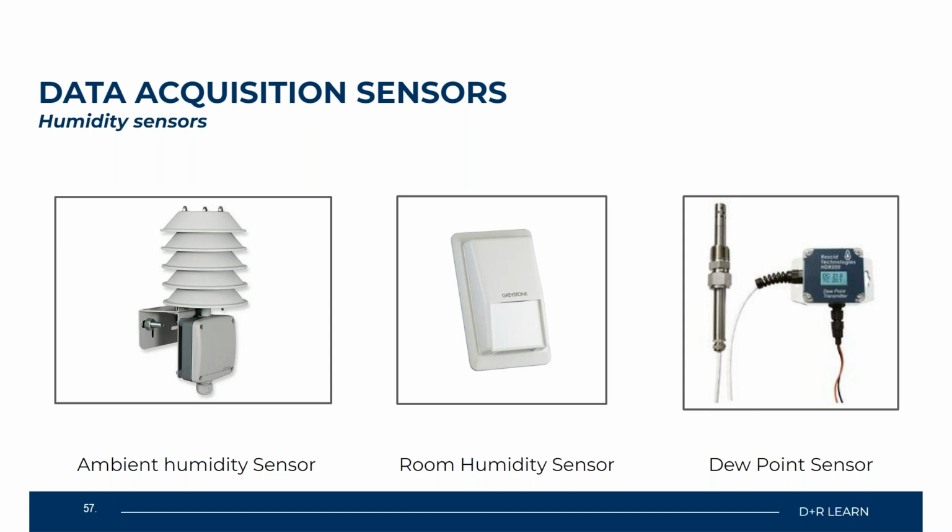If you have an ambient humidity sensor attached to your facility on a commercial level, you don't have to do any type of adjustment. Your building automation system is going to receive that high relative humidity reading from that humidity sensor, and it will send it to the BAS controller, letting it know, hey, we have extremely high relative humidity, and we're going to need to account for that relative humidity when the system comes online.